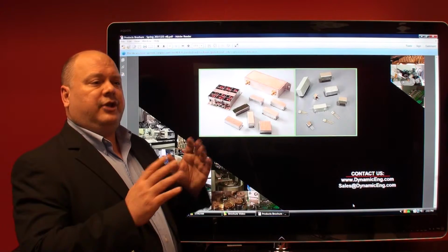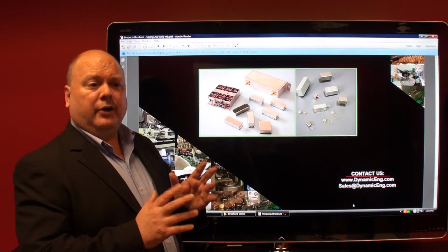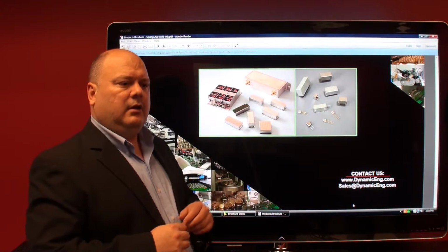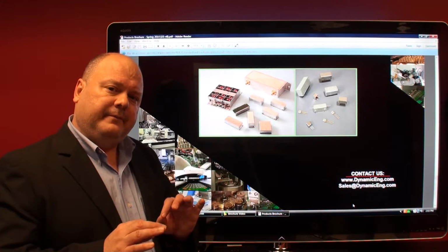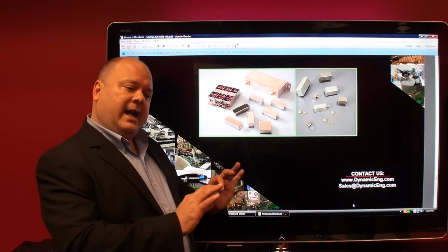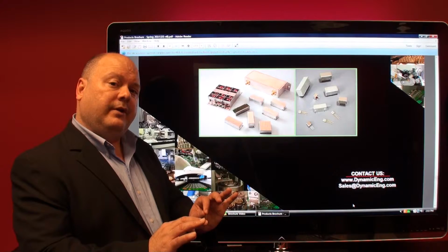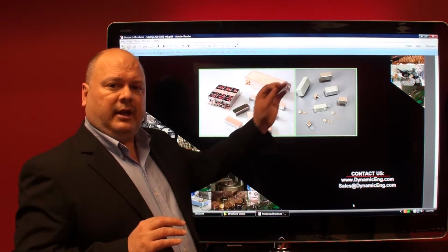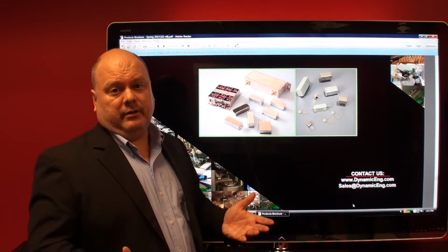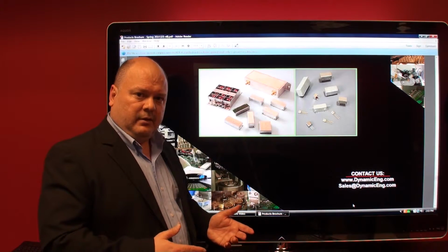So the kilohertz channel spacing for a multi-channel mobile radio, let's say, VHF, UHF, there's going to be an IF frequency associated with that radio. And again, the IF portion is going to be associated with the receive chain, the receive part of the radio system, the low power part, the milliwatts part.